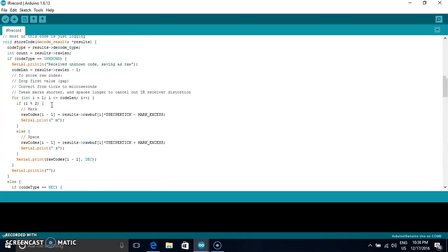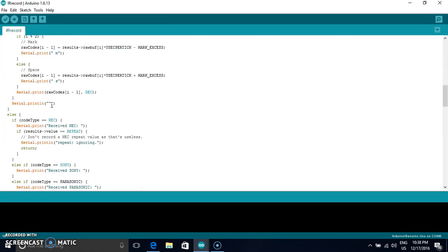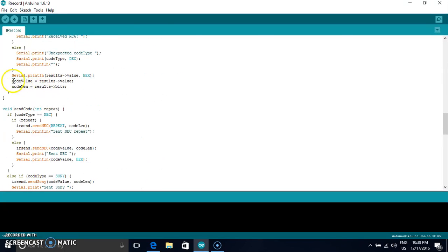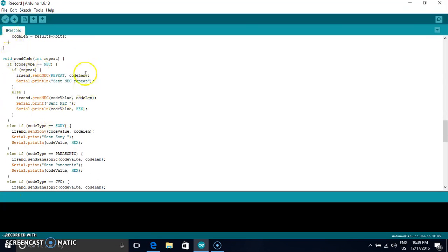So here in this program we are interested in code value. Whenever we press button on remote control, certain code value is generated corresponding to that button, and so read this code value, and depending on this code value perform certain action. Okay, so we are going to write logic like this. So for that, what we'll do, we'll save this program by giving some different name.